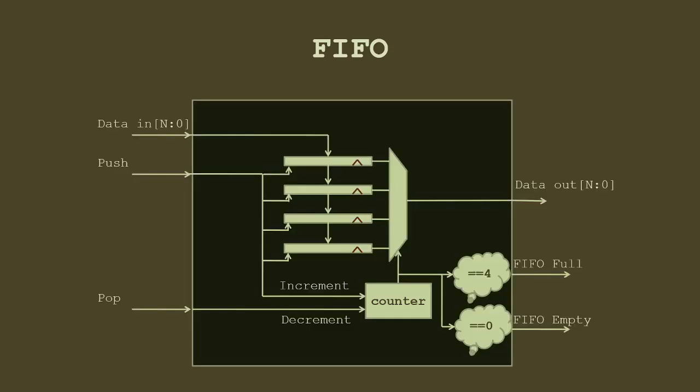So again, what I want to show with these examples is that until we have this level of design diagram available, we don't write Verilog code. We have to reach this stage, unless we have this design diagram. If we don't do that, we'll make mistakes and we'll be writing in a software style, and that doesn't work in hardware.